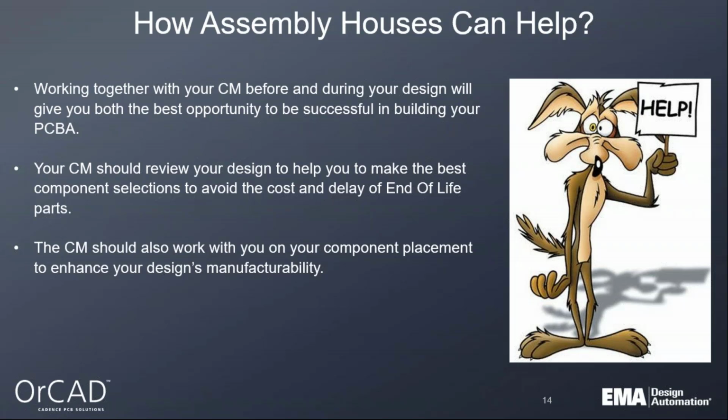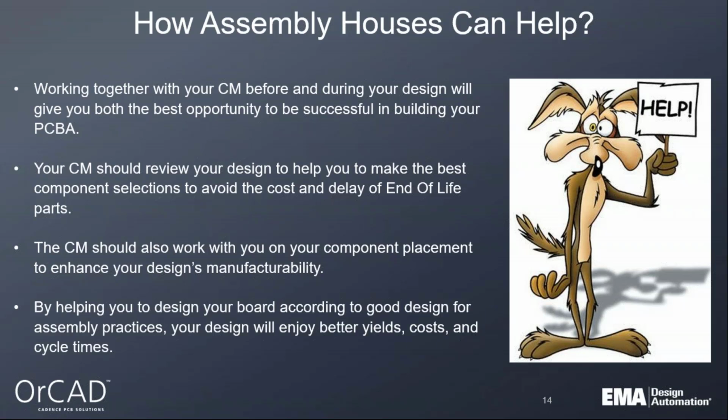The CM should also work with you, like I said, on component placement, but also on the manufacturing of that. They'll be able to run that through their manufacturing checks to find out if you've got the right component sizes on the correct footprint. So it's definitely a good idea to work with your contract manufacturers, whether it's your fabrication house, or maybe they're also your assembly house. So work with both of those.